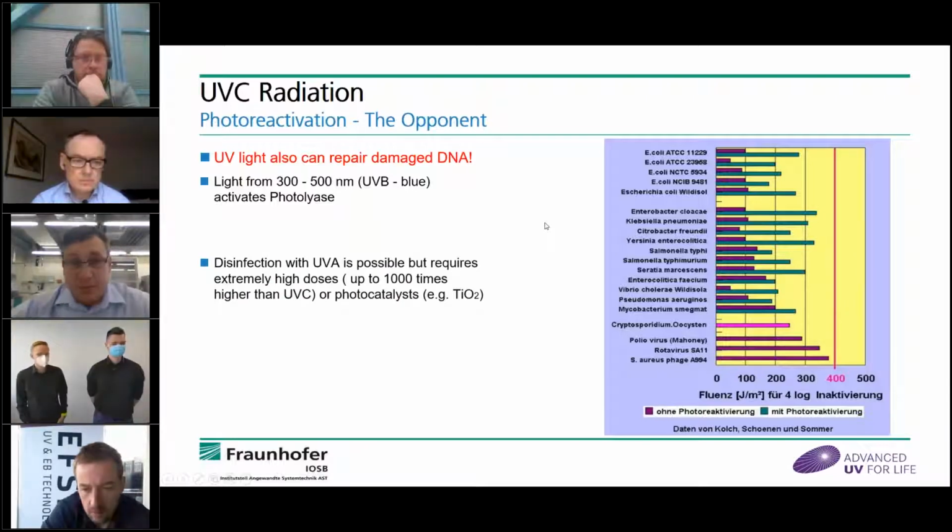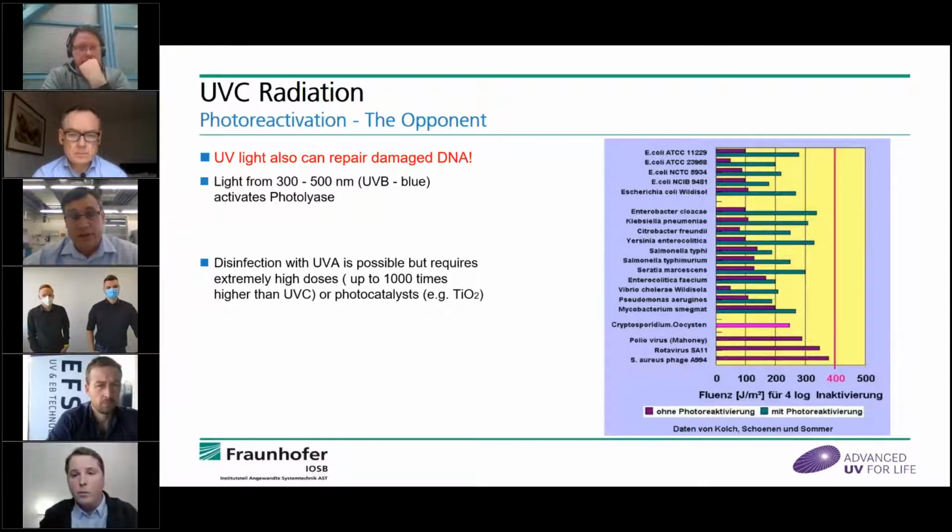But disinfection is also possible with UVA. You will find some systems on the market, but you will need very, very high doses. They can be up to 100 times higher than in UVC, if you use UVA, like 390 nanometers LEDs, or you use photocatalysts to produce radicals.